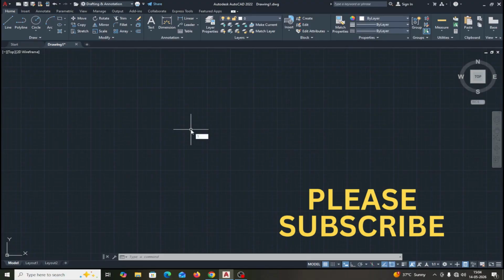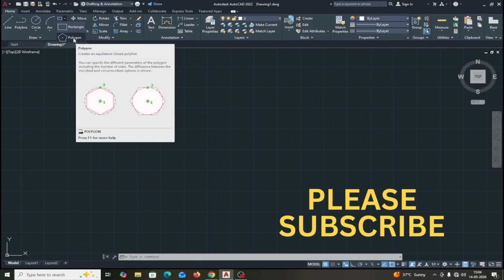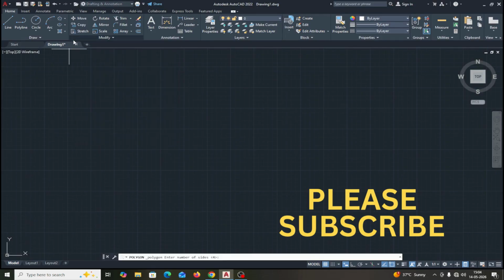Hello everyone, in this exercise of AutoCAD we will understand the polygon command. In the previous exercise I explained all the options of the rectangle command. Now I will explain the polygon command. I am selecting polygon here. Now it asks to enter number of sides.